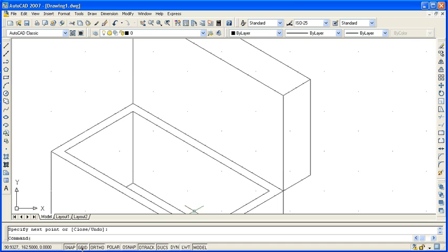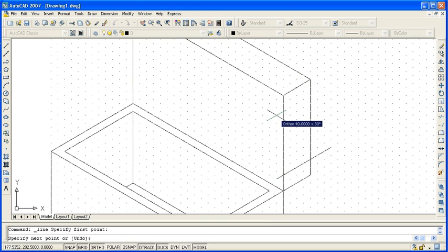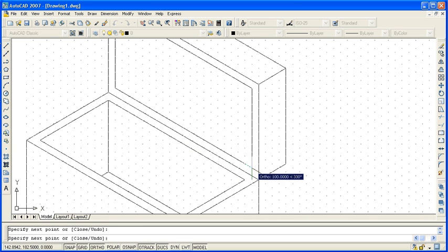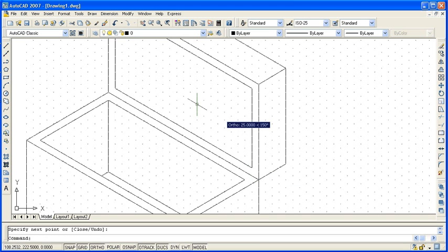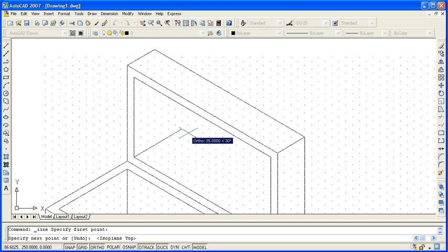So now this grid on, select line command, go to the corner grid, use F5, go to the next corner grid inside the rectangle, use F5 to reach the other corner, and select, and select, enter. The inner edge, visible edge must be completed.